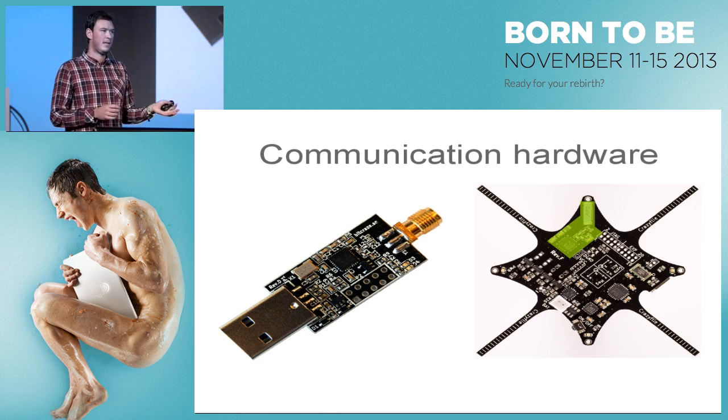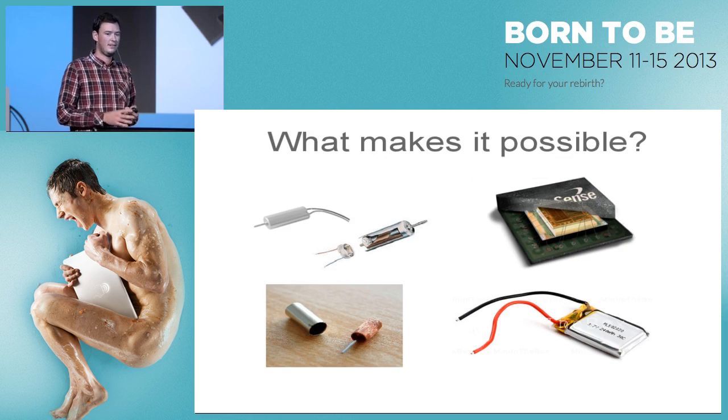You can send packets back and forth, and it has a range of about 80 meters in good conditions. You can have a lot of channels, the full 2.4 gigahertz band. And because we used this chip, we also had to develop a radio dongle ourselves, which was a bit of a drawback, but it was a lot of fun.